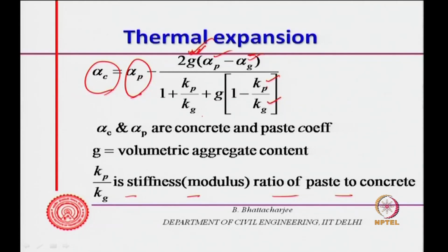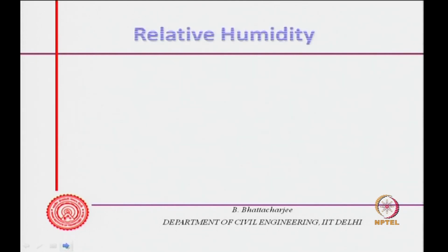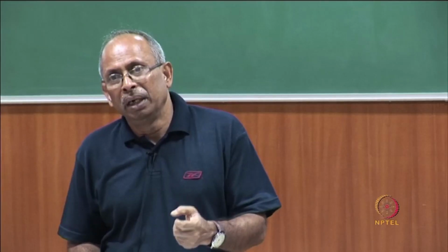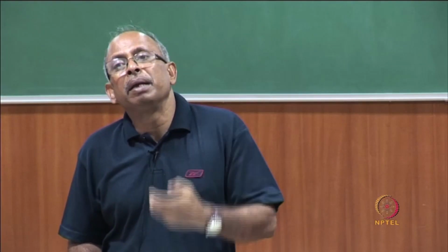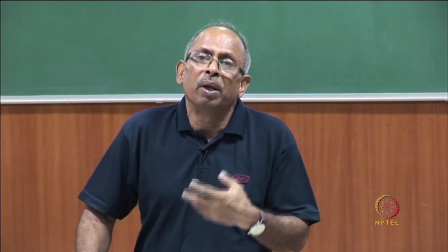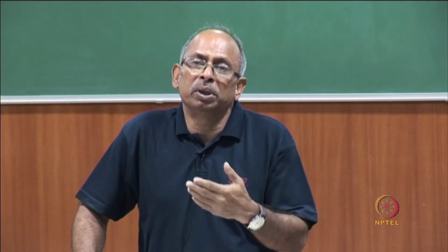So, this is an empirical sort of equation. Another factor which strongly affects it is the moisture content or relative humidity. Moisture content affects most of the properties of the concrete system, like thermal properties particularly, because if you look at thermal conductivity, when you put in moisture, air gets replaced by moisture itself.